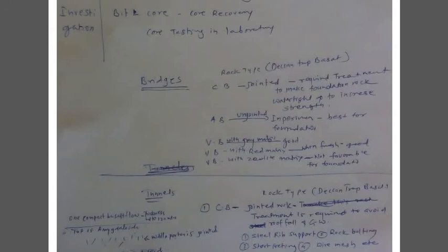Now, drilling on the basis of the geological section: take at least two drill holes, 10 meters away from each portal of the proposed tunnel. This one is important. You have to take at least two drill holes at each portal, 10 meters away from the proposed tunnel.